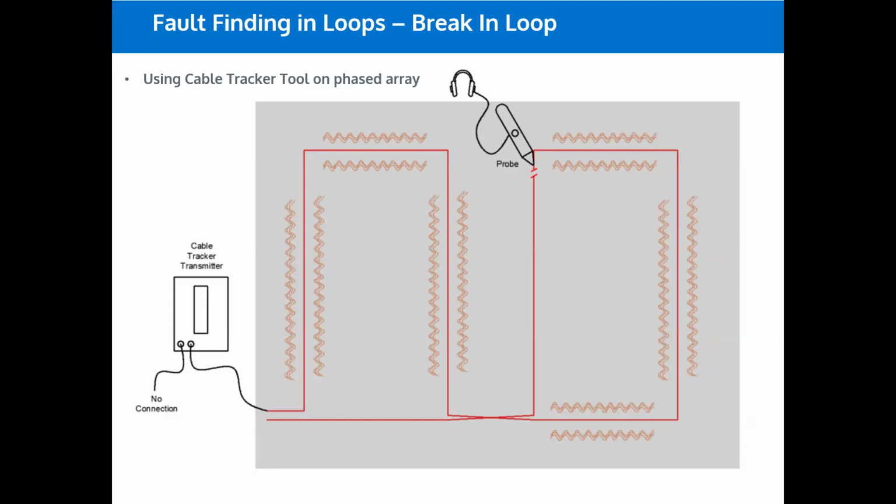Okay, Dave, carry on. The cable testers that I've used and experienced, you have to connect one side of it to one end or the other of the loop, and the other end needs to be connected to earth ground from an outlet as a reference, and you get a very, very strong signal. It doesn't go away on the opposite side of the cut, but you can hear the volume difference from one side to the other once you pass over it. So that's how I've used them.